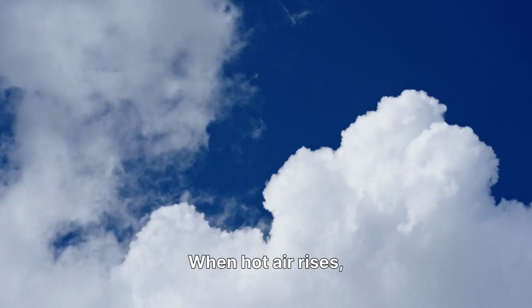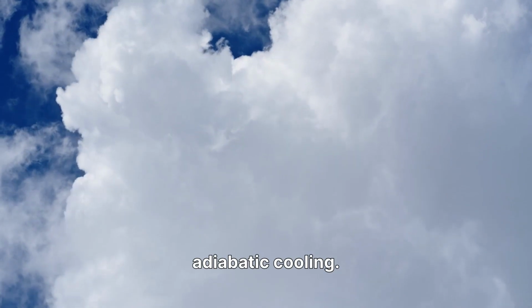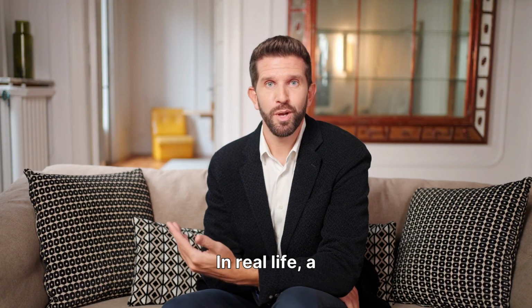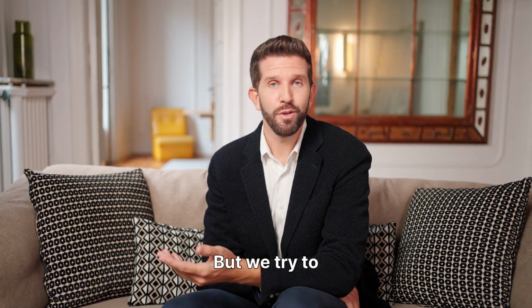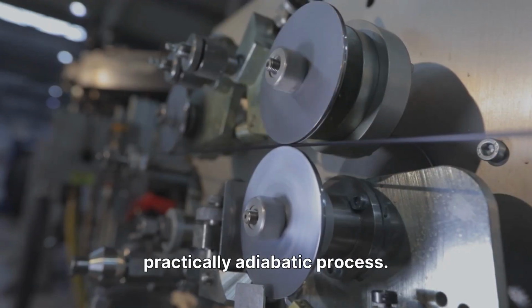When hot air rises, it expands. Its temperature decreases. Clouds form. This happens due to adiabatic cooling. A fire piston works like this. Air is compressed suddenly. Temperature rises rapidly. Fire starts. This is also adiabatic heating. In real life, a perfect adiabatic process does not exist, but we try to achieve it by very fast operation and good insulation. We call such cases practically adiabatic process.